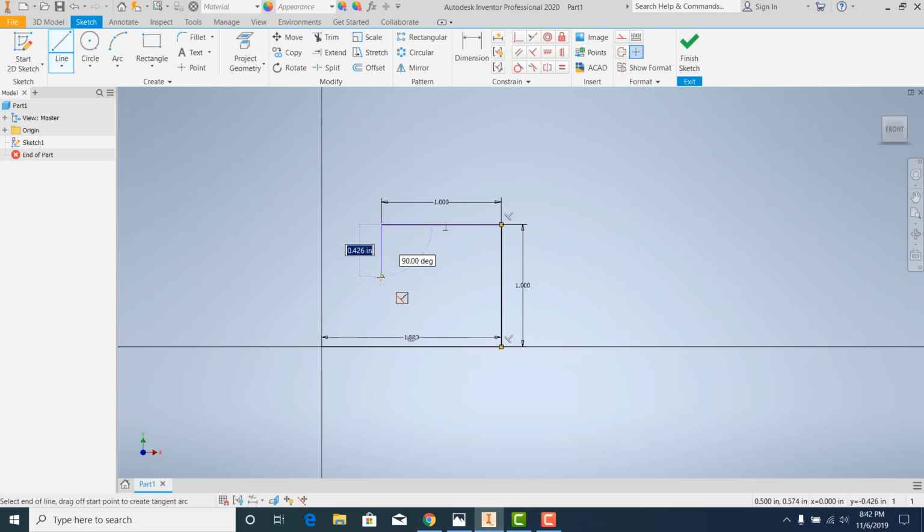Then I'm going to come down, and I'm just drawing that shape, 0.5 because I'm coming down 1 block. Then I'm going to go over 1 block, 0.5, and then I'm going to come back down, and it's going to turn green when I hit my mark, and I'm going to do a final left click on the mouse, and now I have the shape of my part.